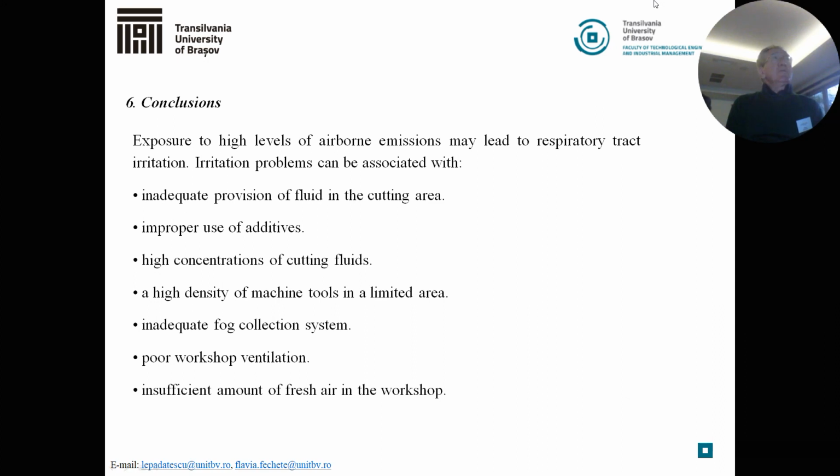As a conclusion, exposure to high levels of airborne emission may lead to respiratory tract irritation. Irritation problems can be associated with inadequate provision of fluid in the cutting area, improper use of additives, high concentration of cutting fluids, high density of machine tools in a limited area, inadequate fog collection system, poor workshop ventilation, and insufficient amount of fresh air in the workshop.